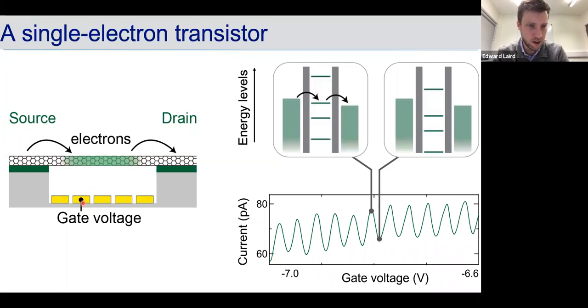By a combination of the Schottky barrier at the interface and by tuning the gate voltages, we can tune the potential so that the central part of the nanotube is conducting. It contains either electrons or holes. And then on either side, there's a barrier. So we have here a quantum dot, which has Coulomb blockade,